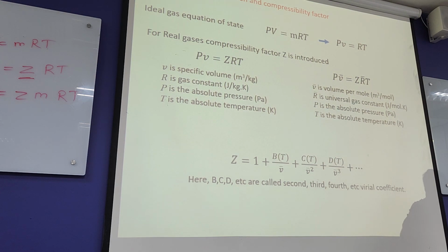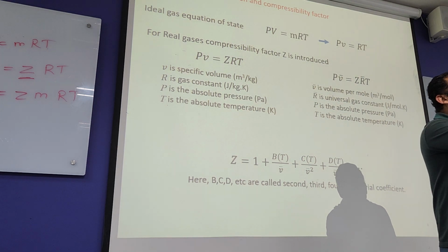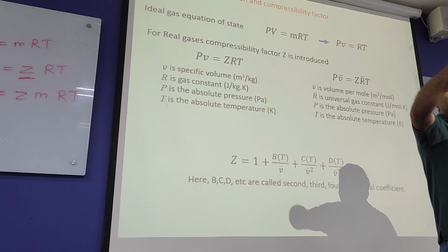Take a rigid tank like a pressure cooker, put some gas in it and start heating it up. What's going to happen? You start heating it up, temperature starts rising, volume is constant so volume doesn't change, hence pressure starts rising. So you can measure pressure and temperature and come up with a curve, for every half a degree temperature rise, you measure the corresponding pressure.